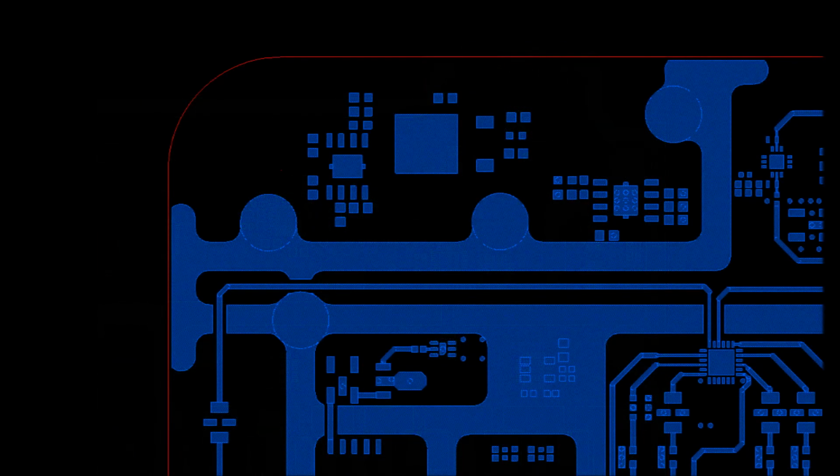We also have to add a shield wall around the board outline. However, because there may be several iterations of making the internal shield walls as the design progresses, it's best to leave this part until the end. The conductive shapes for the internal walls take this into account, with a smooth transition being made in the area where the internal walls will meet the board outline walls. The internal walls can be drawn, deleted, and redrawn again, and no matter where they intersect the board outline wall, there will always be a smooth radius to connect the two. When the board outline wall is added at the end, it will overlay the wall shield areas without any sharp corners or discontinuities.